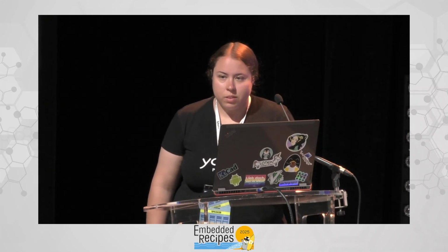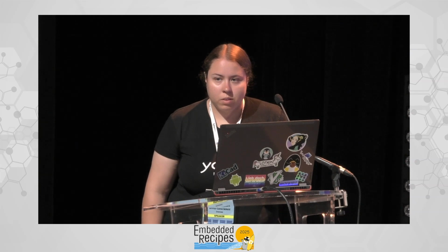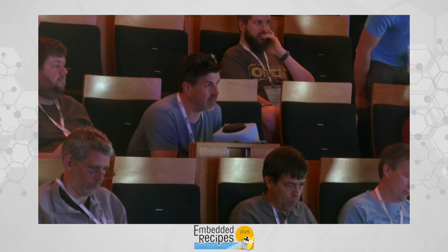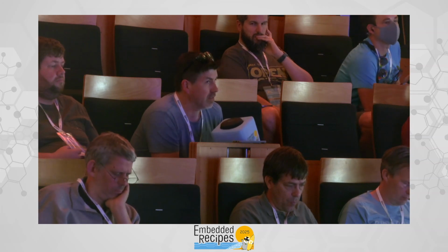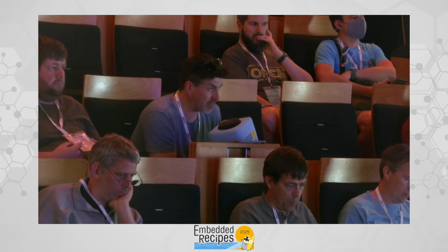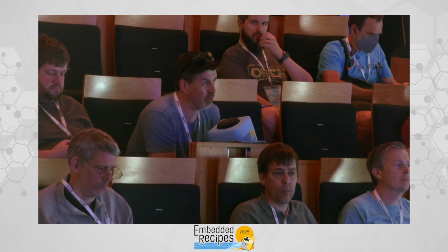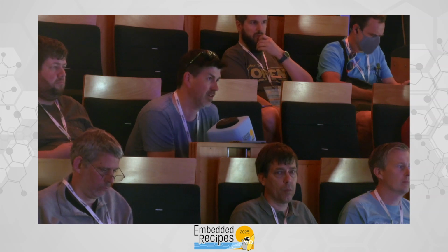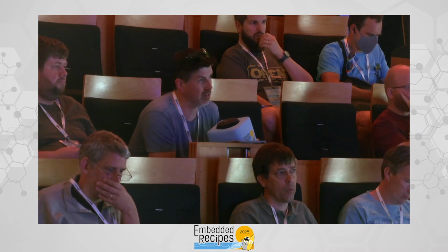So continuing to the PCR questions, a use case that I often meet is that if we want to include GPL3 in the firmware, we cannot really use secure boot, because that would not allow the user or the owner of the device to actually flash new firmware, modified firmware at least. So instead we want to use measured boot only, and then unlock the data partition only if we boot something that we trust. But how does that work with an A/B update scheme? Can you have multiple PCR hashes bound to an encrypted device, so that you can actually update the other partition and say this is also a valid boot sequence?